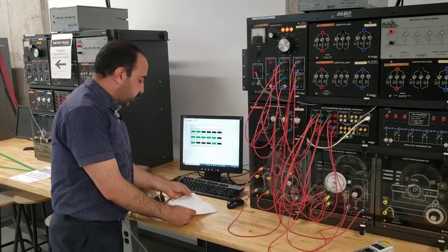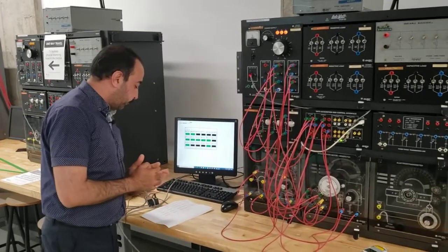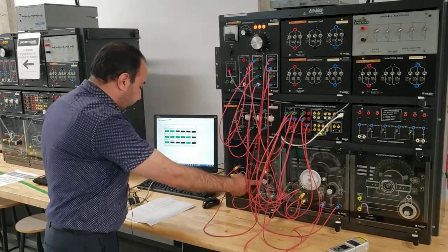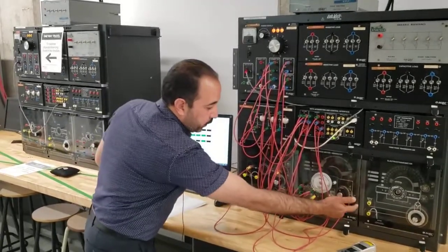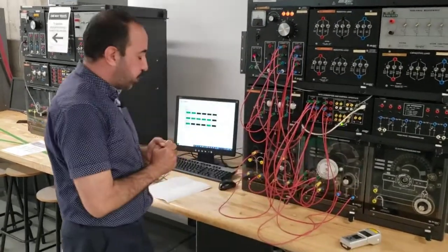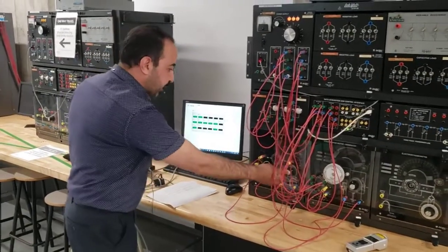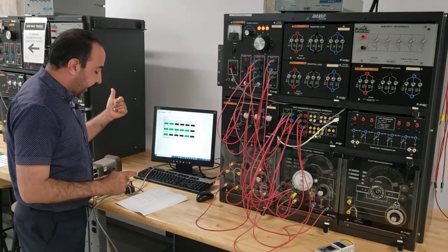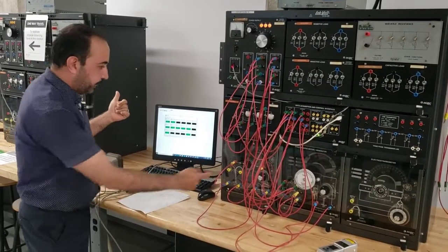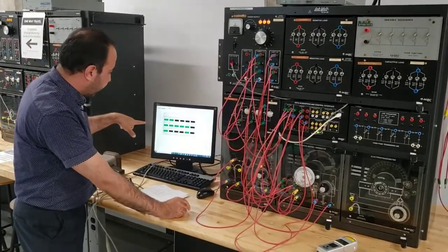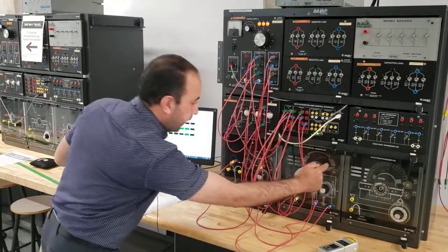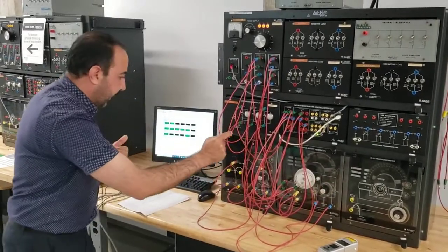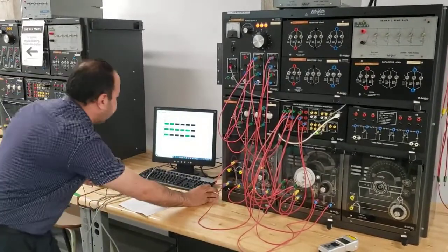I would like to change the field current for the DC machine, because I would like to work under constant excitation for this. So I will not play with the excitation, and I will try to adjust the speed, and I will try to measure the currents IA for the DC field, and IA for the synchronous generator, IF, which is this, and I would like to measure the power factor and the power.